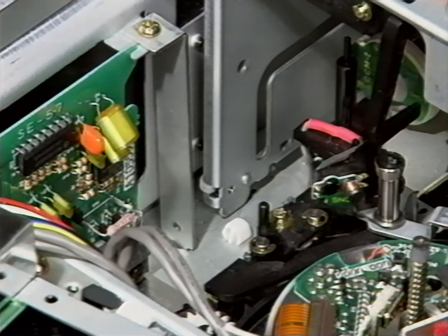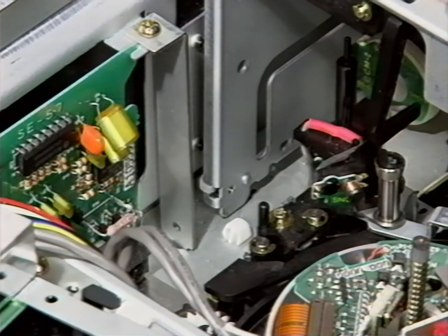Cassette compartment. If the cassette compartment foot is not placed correctly in slot, the unit will go into auto off. An error code will be displayed. Error 20 is the cassette loading problem. This problem can also simulate a reel or a tape height problem.